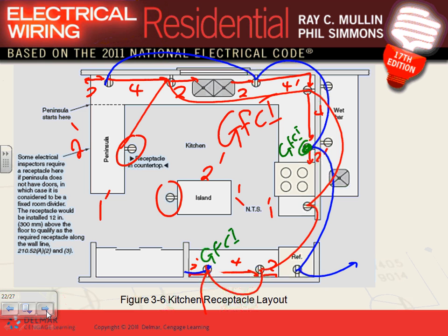They make a big deal in the book about not putting the fridge on the countertop. You can, but it's good design to throw a circuit. You're allowed to throw an extra 15 amp circuit for the fridge. The code says permitted. So if you guys want to take a fridge and have a circuit for it, that's fine. I think if you do 2 20 amp circuits in a kitchen, you know how much juice you can get from a 20 amp circuit. If you do it right, I think you're good, unless you have a really huge house and you entertain a lot.